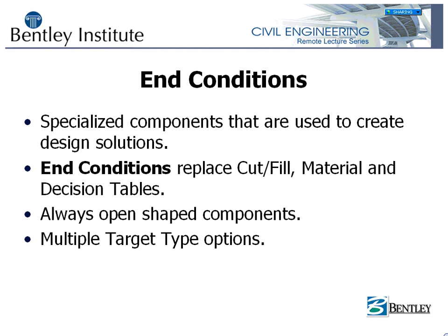Okay, so what is an InRoads condition? As you can see, it's specialized components that are used to create design solutions. Conditions replace cut fill, material, and decision tables, and that's kind of why I wanted to talk about conditions in non-corridor design situations, because a lot of these tools were used in non-corridor design or site type work there. Conditions are always open shape components, and we'll talk about that in just a minute as we start creating some conditions, and we have the ability to do multiple target type options.